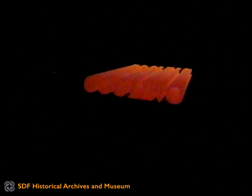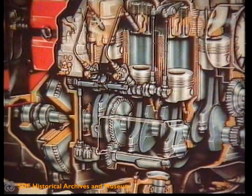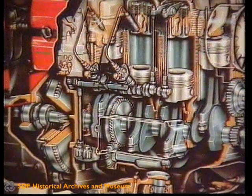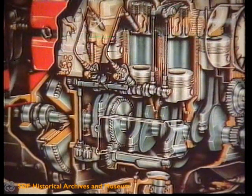Engine cooling on the right-hand side. The cooling air is captured on the right-hand side of the engine where the greatest heat develops, thus giving greater cooling efficiency, where the injection pumps are located. Improved injection output, since, due to the cooling of the pumps, the fuel is pumped at a lower temperature and therefore at a greater density.